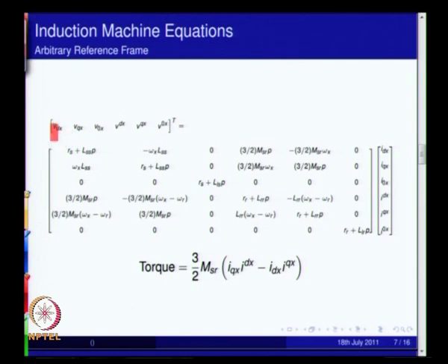These are the voltages along coils that are now imaginary coils rotating along with the dq axis, lying along the d axis, q axis and the 0 axis. Similarly for the rotor coils, d axis, q axis and the 0 axis, these are the voltages that are applied. Those are related to the flow of Idx, Iqx, I0x etc. by this description.